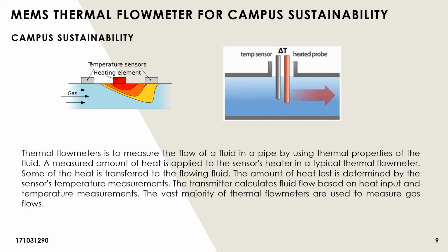Many of these applications present opportunities for thermal flow meters, including measurement and recovery of landfill gas, monitoring of flue gas, and measurement and monitoring of flare gas flow. Thermal flow meters are uniquely suited to make this measurement because they can accurately measure different mixtures of gas, and because their insertion technology allows them to handle large pipe sizes.